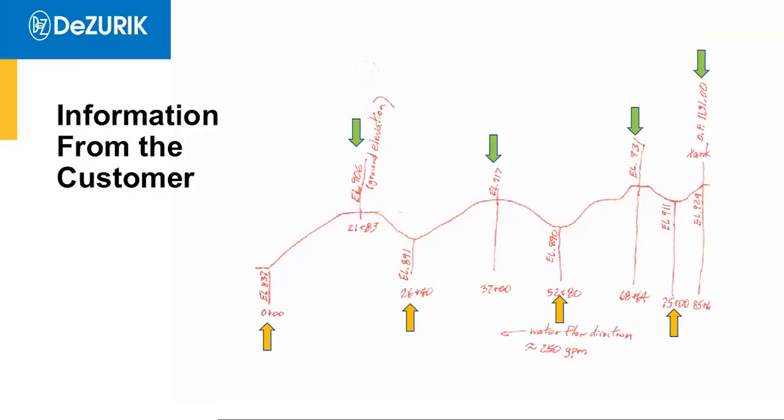So I had to do one calculation, which was to reverse the station distances. Nothing else changed, but if I was going to start with flow in one direction, I had to start at 0 and calculate what the distance is to the next station and so on. So pay attention to flow direction. The program does care about that. Okay.